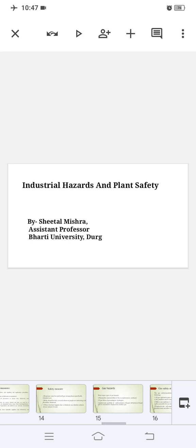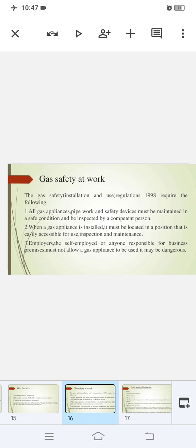In the pharmaceutical industries, dust is controlled by methods at the source of generation or propagation of the dust. So what are the various methods? First of all, filtration, second is inertial separation, and third is electrostatic precipitation. What happens in filtration? Filters are mechanical barriers consisting of fibrous, felted and porous media, and these are one of the most effective devices for removing dust particles.